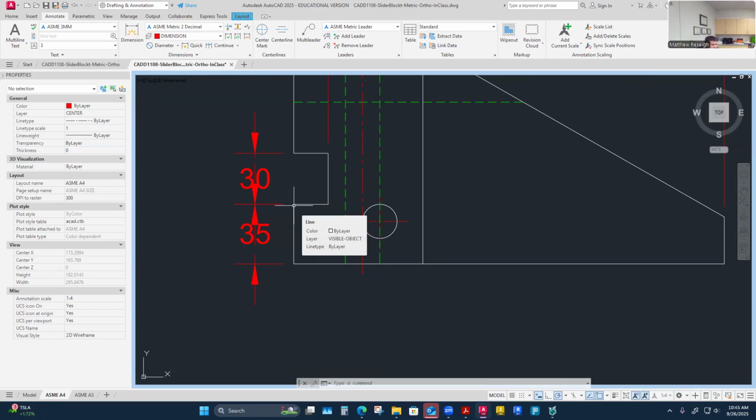and then they pull from that point to the next point, which is 30, you get what I call tolerance stack up. It means they didn't hit the dimension exactly right. Then they based the next point off that dimension, which is now slightly inaccurate, and you're starting to stack up problems. You're starting to have this tolerance stack up, which can drastically make parts unacceptable.